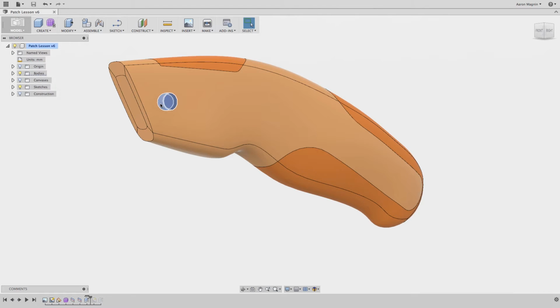In this case, the tab on the left side was added too early in the design stage. To remove it, all that's needed is to select the connected faces and hit the delete key. Using that same methodology on the front of this model, where we wish to smooth out the end face, behaves differently. It does nothing. This is because without connecting faces, the software cannot infer how the user wants those faces